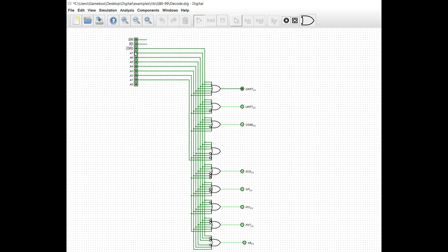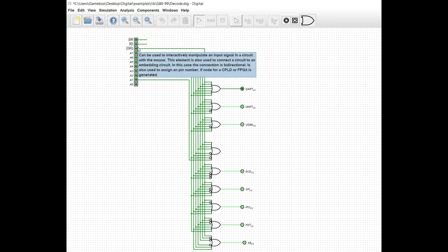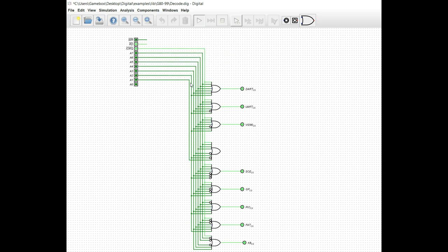Okay. So as we fire it up, we see UART is automatically asserted, and that's because A7 through A2 is low, and IO request as well as read and write are all low. Of course, read and write are not currently used, but we can get the idea as far as what we need to do. So we know that if we just cycle IO request on and off, we're going to get a low on the UART. Now if we go to the UART and we set it to address 08, we're also going to get a low.